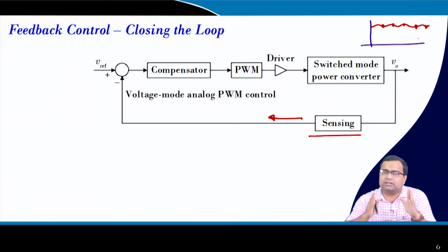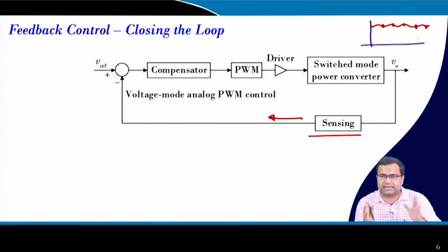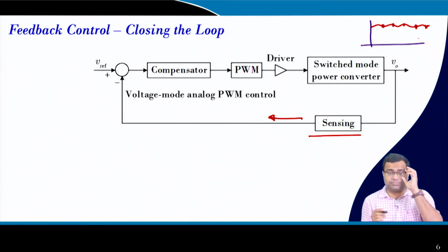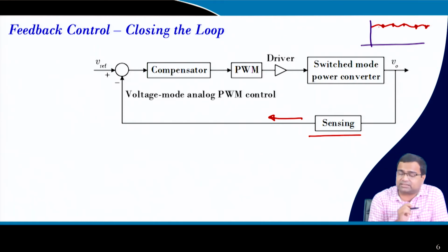So, as long as our actual transient response using the small signal model is matching with the switch simulation under closed loop, up to that point we can increase the bandwidth. Beyond that, there will be mismatch and our model is not valid. So, that means we need to slow down this process because of our small signal model.